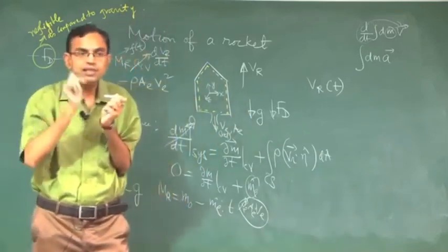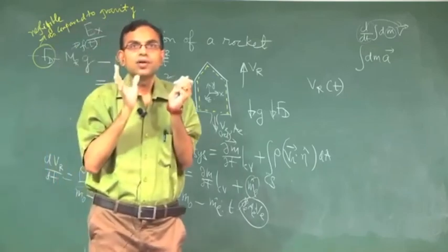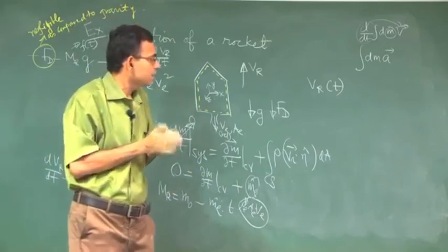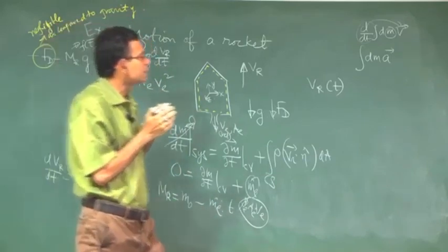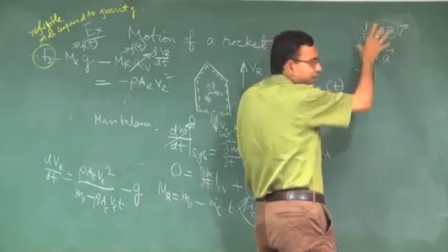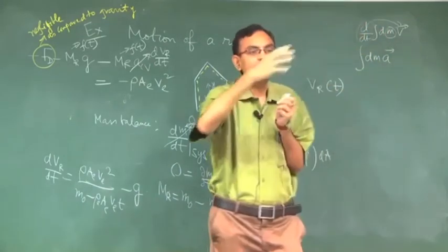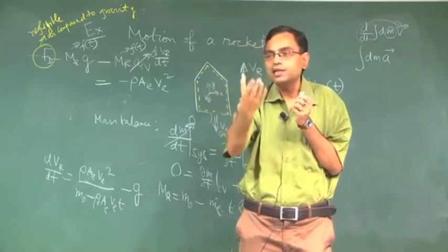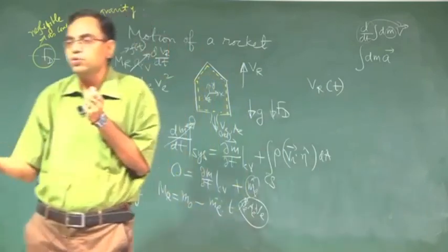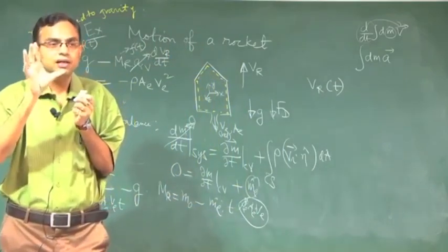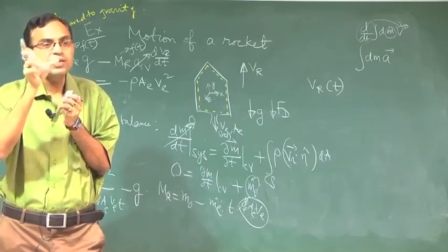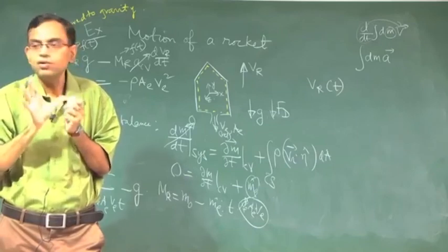So this is a subtle concept, and this is a contradiction. All of us learn through contradictions, and this is a very important contradiction. The contradiction comes from the fact that you have a variable mass, but still you are relating it to an equation which fundamentally relates a control mass system with a control volume, and control mass is by definition a fixed system mass. So this is instantaneously treatable as a control mass. That is how you have to interpret it.